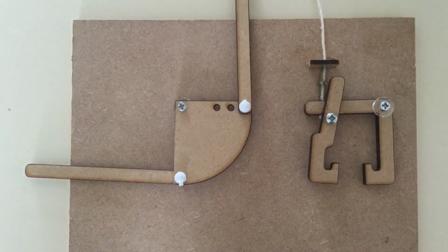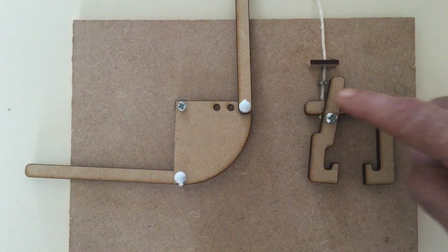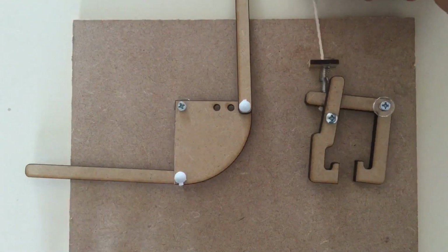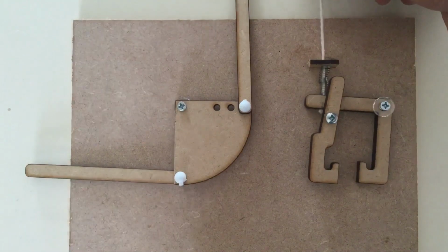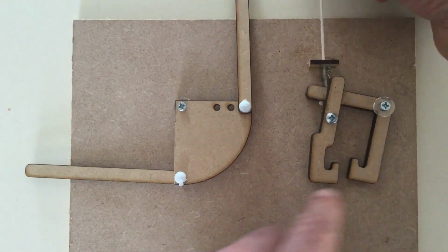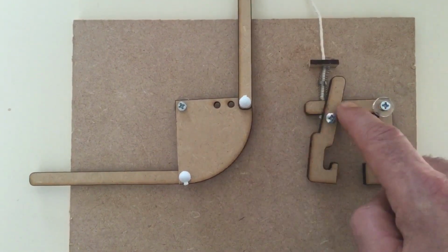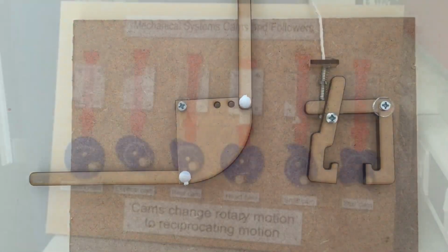I also wanted to show you a version of the bell crank mechanism that's commonly used in bicycle brakes. It's this part here. When you pull it, you can see that the input of pulling the brake cable is vertical like that, whereas the output is moving at 90 degrees to it in that direction. It's exactly the same principle as this. It's a bell crank. It's just that the actual crank itself is a different shape.